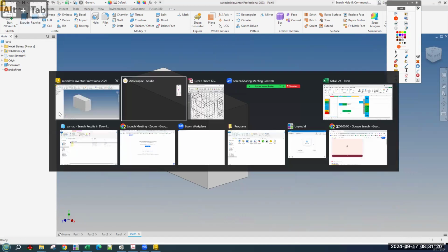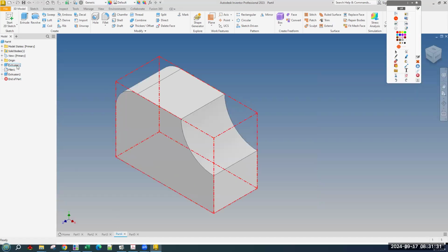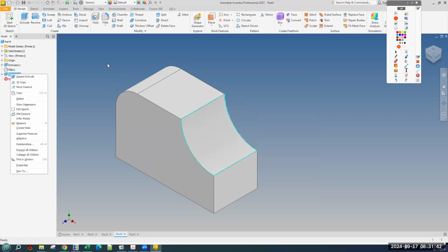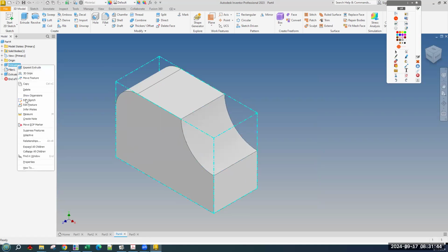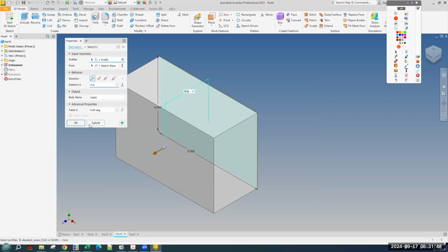Okay, and the only other part feature is this cutaway, which I want to make sure that we are using the correct terms. Everything over here is a part feature. This one from part 9, we made an extrusion. That's our first part feature. The fillet was our second part feature, and the cut extrusion was our third part feature. If you right click, edit feature, that's what you're adjusting: the extrusion, the fillet.